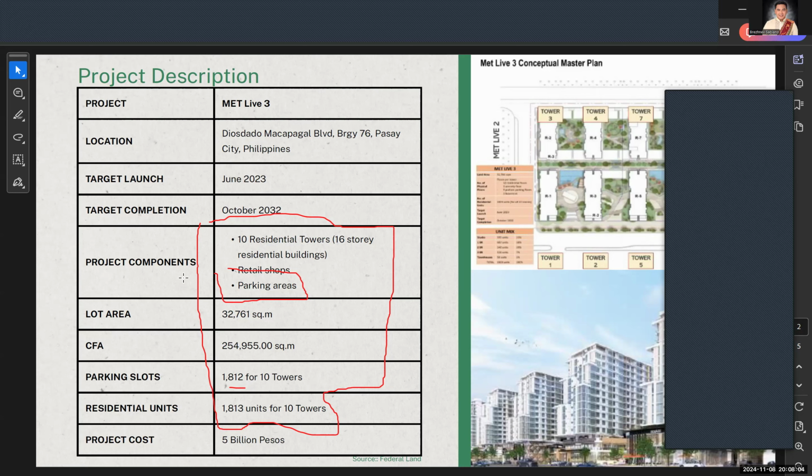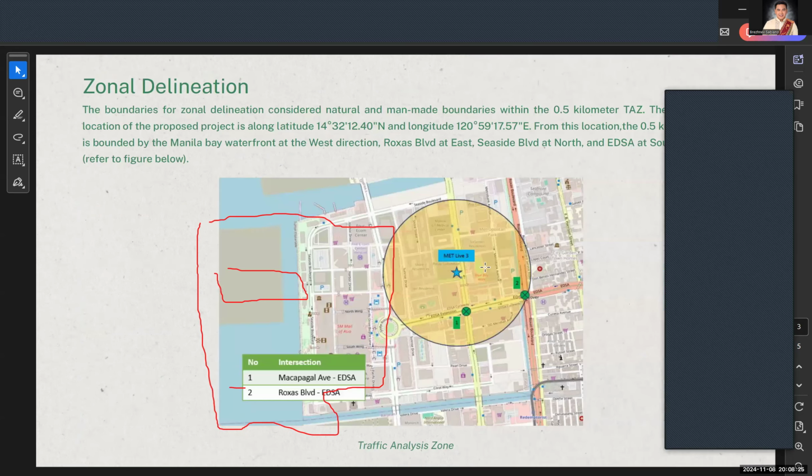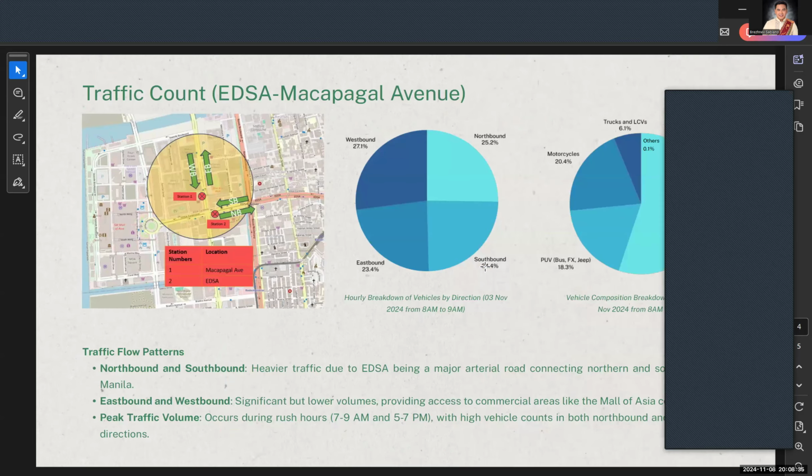Okay, sir. So we can just use the standard, for example, for classification of residential, there will be a corresponding produced and attracted trips rate. Correct. And then multiply by these numbers. Okay, noted. So for us, the manual traffic count is better just for comparison purposes. Correct, only after you build the model, you will compare whether your result is the same or not.